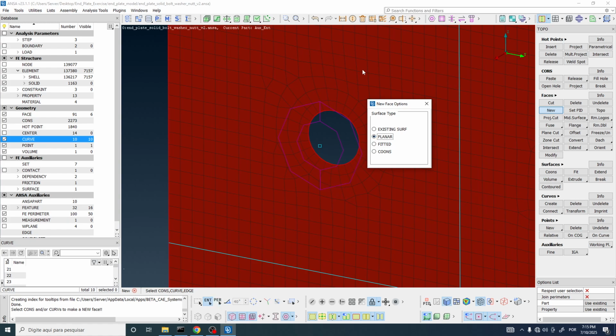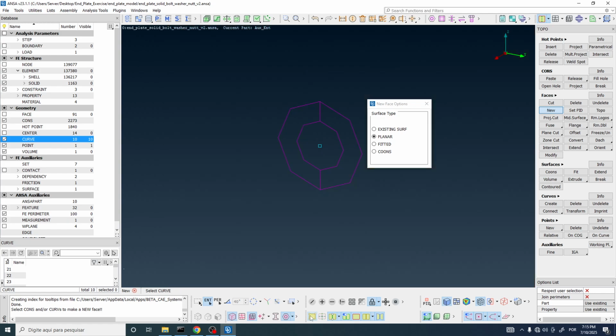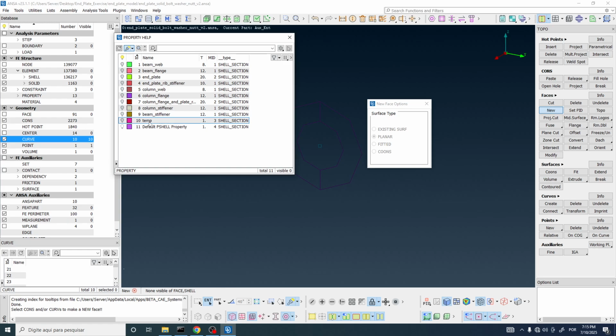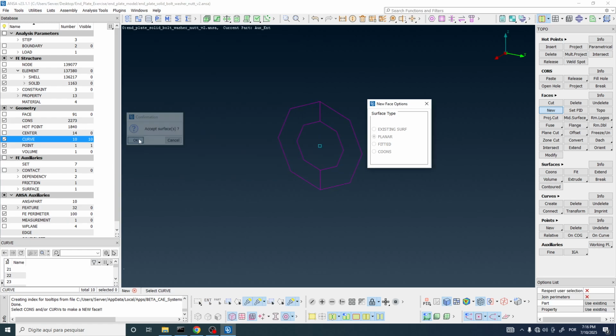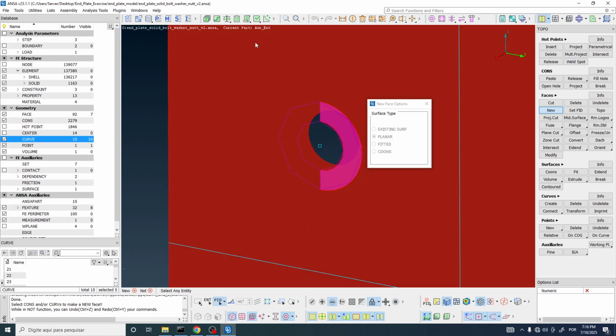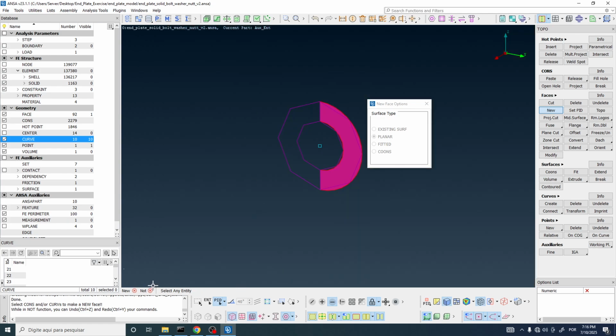Let me hide this mesh here by unchecking these. And also let's uncheck the macros visualization. Now let me create by selecting these cones, middle mouse button. Let's assign this to this temporary property that we have created. Click on OK. We are not able to see it because I don't have macros visible. That's okay. Let's have macros visible, and actually let's use the not function and hide this back PID selection mode and hide this back macro. Deactivate the not function. You see that we have two functions activated here. Deactivate the not function by clicking here.